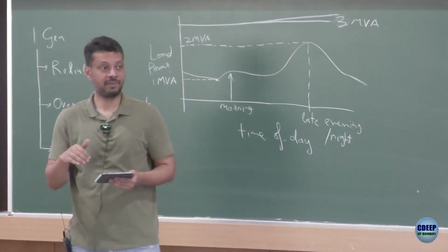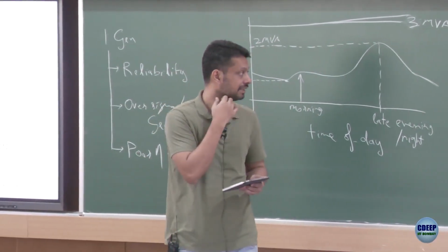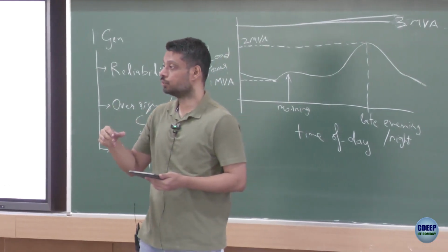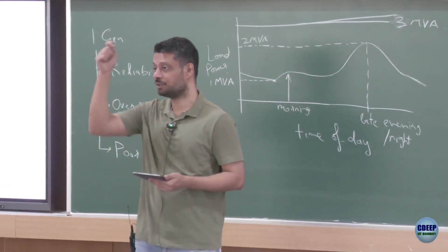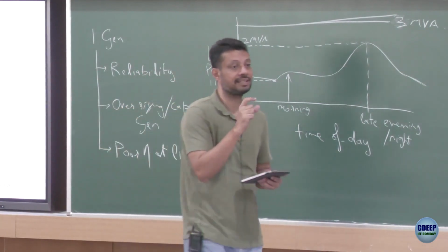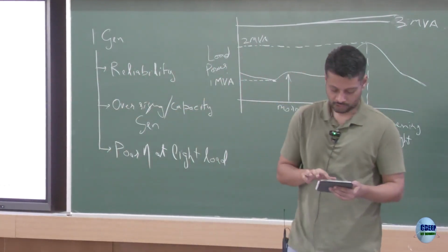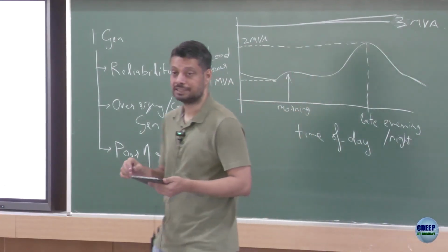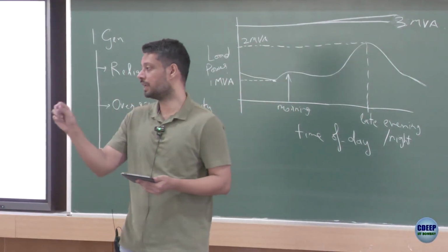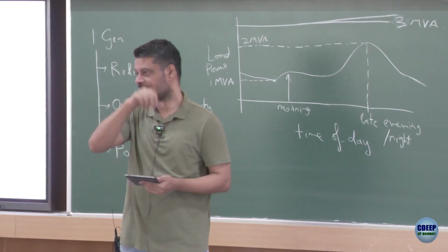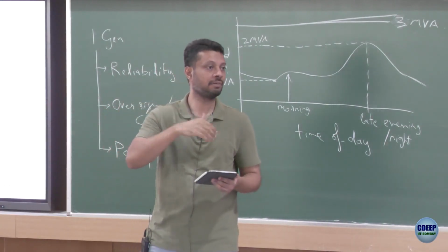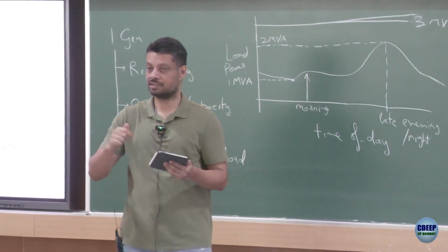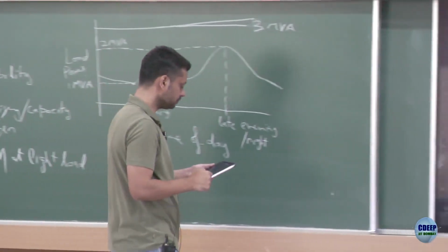But what I am saying is that in December 2013 the whole country got connected through a synchronous link. That means anywhere you go at steady state, you would see the same frequency. The catchphrase was one nation, one grid, one frequency. Anywhere you plug in, you would have the same frequency. Of course, there were still HVDC lines, but they were in parallel with a synchronous line, so that the frequencies at both ends are the same.